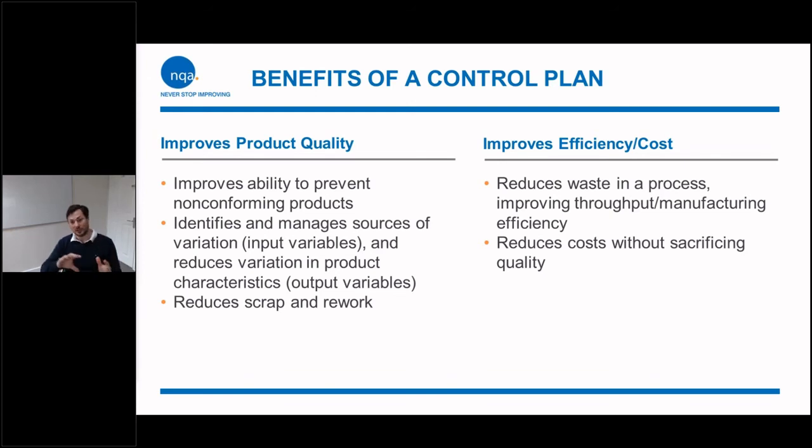I've got some clients that will ask their suppliers to do a quality plan for the products that they're going to manufacture. They'll develop this with the suppliers, and it gives them confidence that they're managing the process okay, and then it reduces their time for inspection when the parts come in.